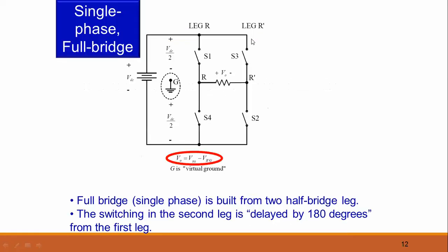Okay. So first of all, the single phase full bridge inverter. This is a single phase bridge inverter. The DC supply is over here. Four switches are used. These switches can be thyristors or MOSFETs, but they should be controlled devices.